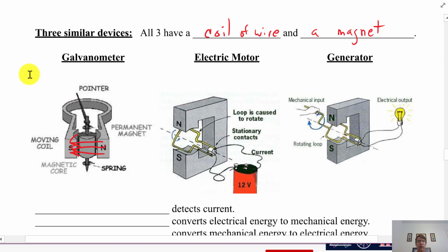So if you put more voltage in there, you get more current, or if you have something so that you can measure, you could use it as a voltmeter, because the more voltage you put in there, double the voltage, you'd have double the deflection on that needle. Or just put more current in there. So depending on how you hook it up, you could use this as an ammeter or a voltmeter, because there's two interacting magnetic fields. Same thing is basically happening in all these other devices.